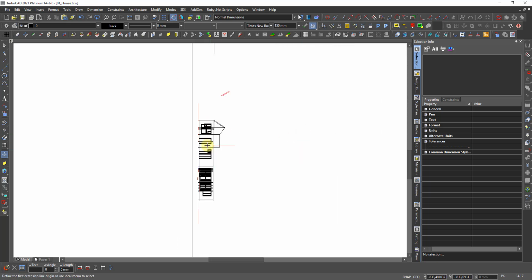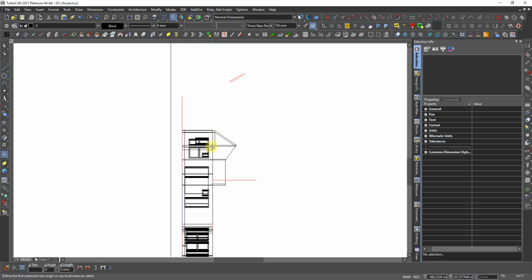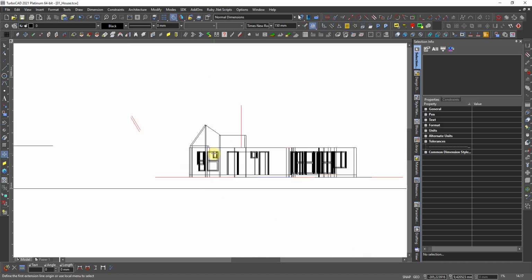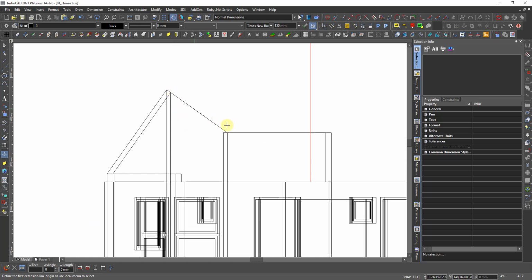Now look there. It will always, or nearly always, come out rotated. So then I press shift and I go to the arrow key and press up. It moves 22.5 degrees every time I press the arrow when I keep the shift down. Now it stands straight. Now I'm looking directly on this wall.